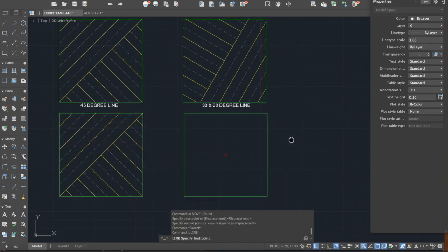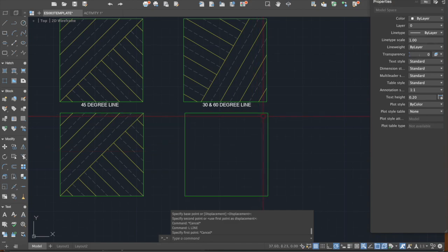So for the center of the object to pop out, create a line, enter, and then move your cursor towards the edges so that it will show up the center point. So you have this one. So click this one at the center and then locate the first angle, which is the 60 degrees. So you have here 60 degrees.